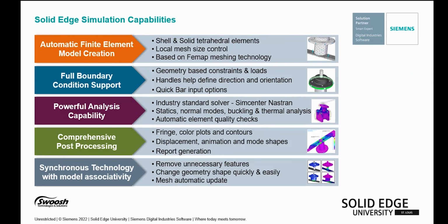Let's take a look at Solid Edge Simulation capabilities. First of all, Solid Edge Simulation provides both automatic and manual methods of mesh creation. It also provides precise local mesh control for higher accuracy, specifically around stress concentrators. A full complement of loads and constraints is available for defining realistic operating environments, because our goal is to mimic real-world situations as closely as possible.